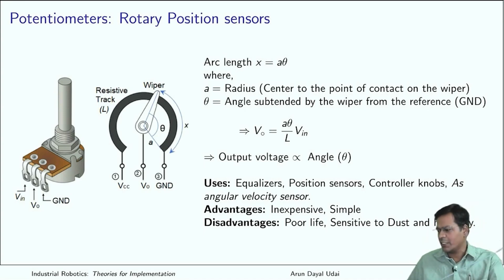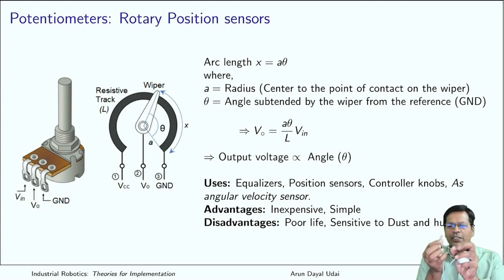This is a potentiometer. You can quickly identify this by counting the number of wires. One is for the shielding, that is system earth, and then it remains with just 3 wires. One is ground, the other one is voltage, and one of them is signal. That's all. So 3 wires and done.